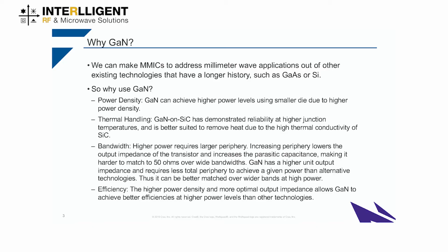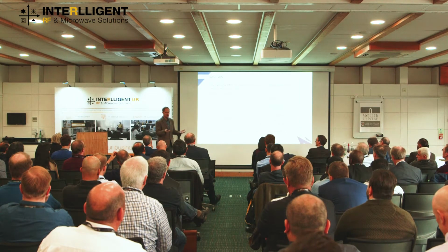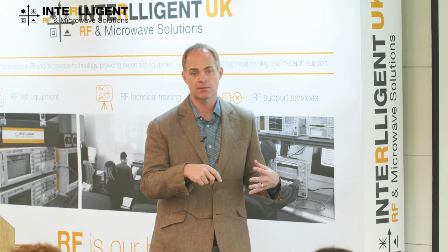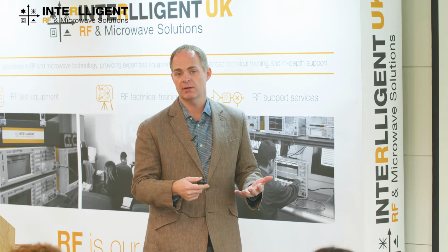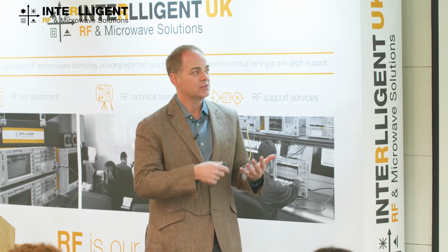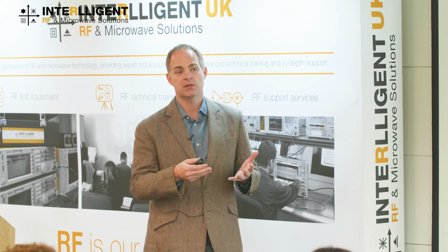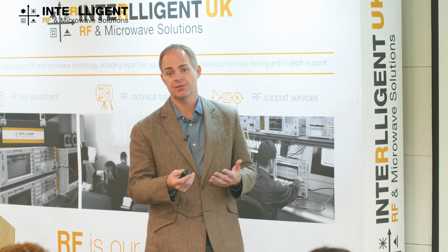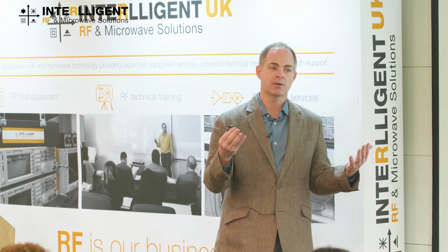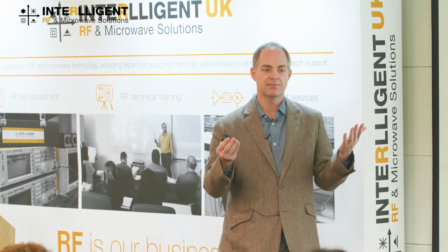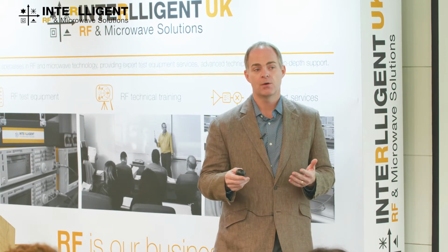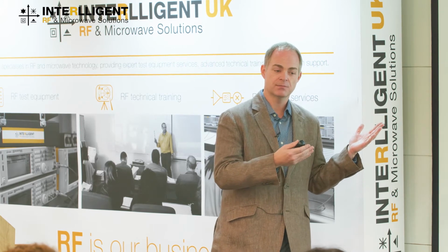As we talked about earlier also, these are becoming not only power hungry, but also much more compact as we move into millimeter wave. So the ability to dissipate and get rid of the heat in your application becomes more and more critical as you move up in frequency. This is also because as you move up in frequency, it becomes harder and harder to achieve higher efficiencies. If you're at a lower frequency, you can get much higher power out of a single die, say, because you're able to do power amplifiers that might have, say, 80% efficiency or more. So high power silicon is useful there.